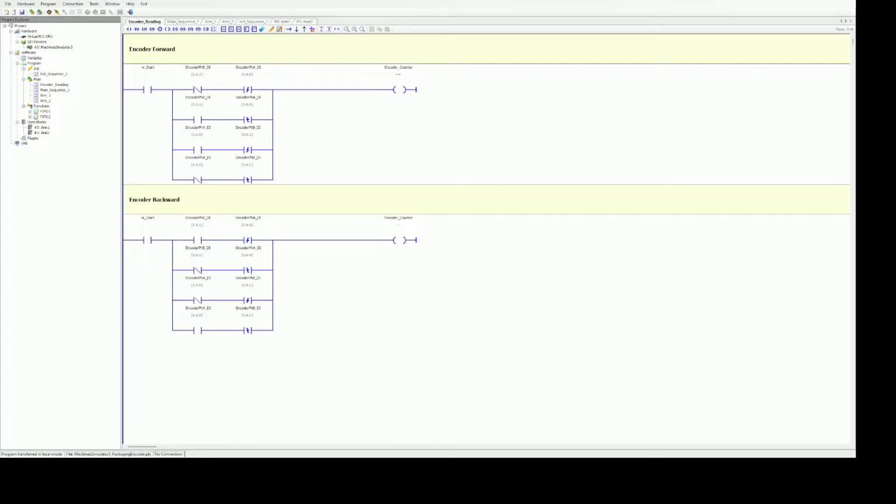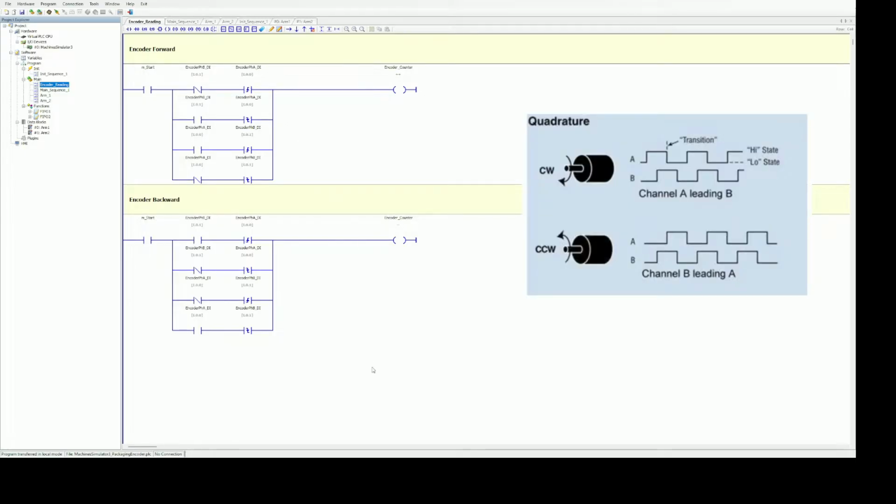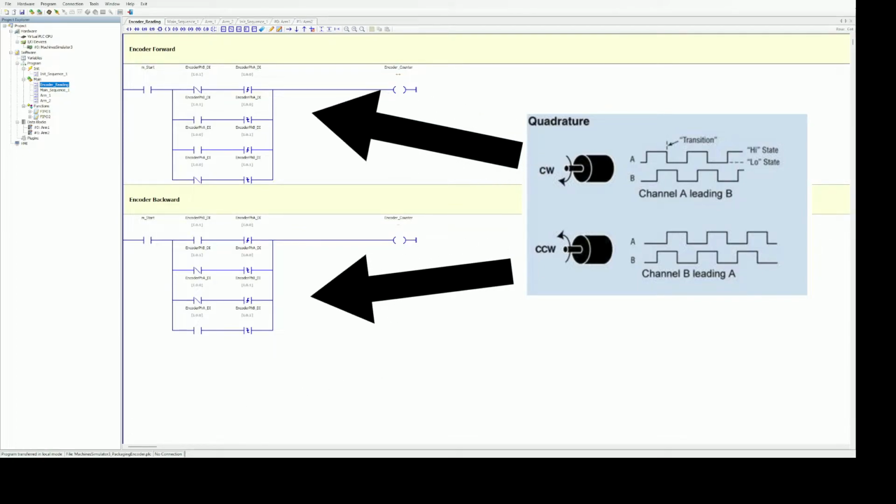In the encoder reading sequence, the 2 digital signals of phases A and B of the encoder are read. In this example we see how the signals for the encoder count are programmed, both in the forward and reverse directions, although in this program it will only work with the forward direction.